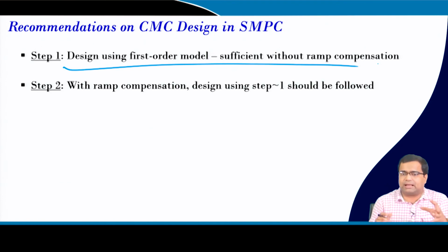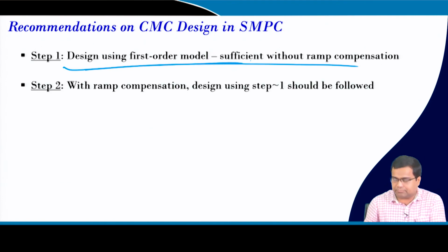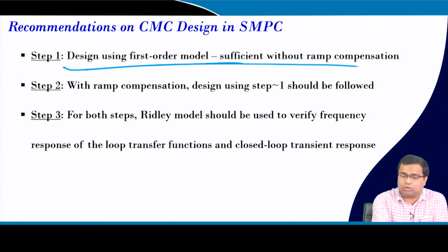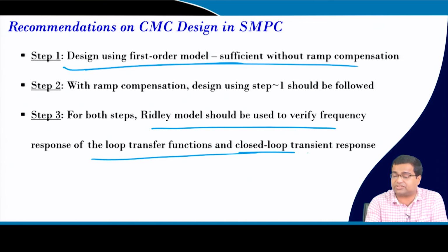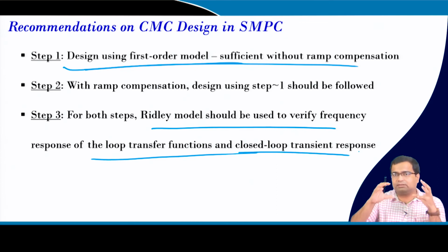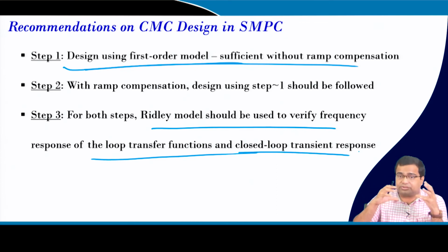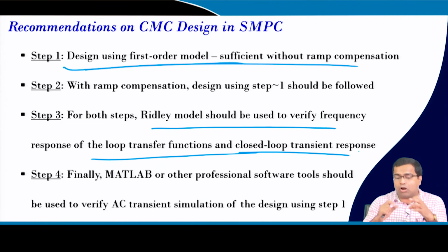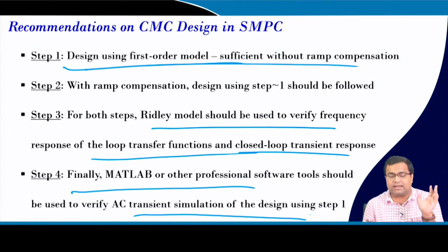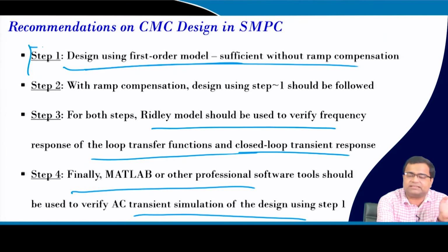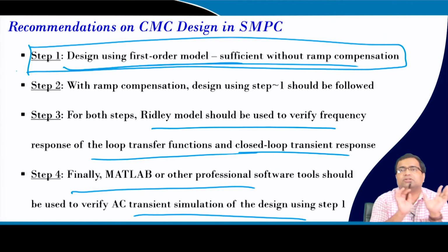If we consider ramp compensation, we can still design it, but we should validate both cases with the Dirichlet model for frequency response matching, as well as the transient response we have checked, the response coming from the transfer function like AC analysis plus DC offset. All should be checked with actual switch simulation, and all we have done, right. So, the final recommendation: we can simply design the current mode control using a first order model.